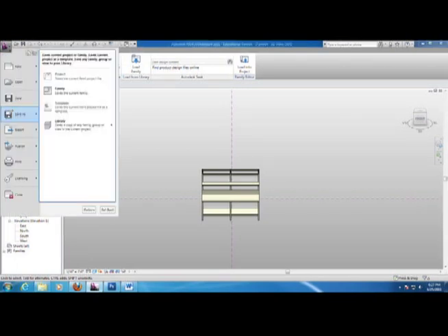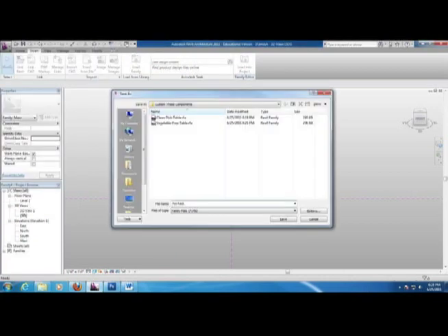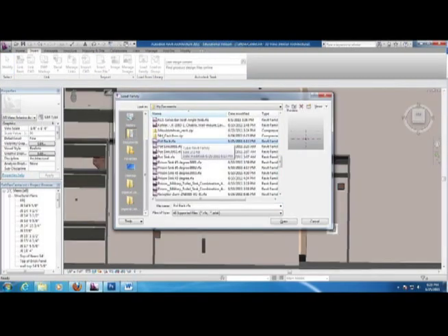Next, click the Revit button in the upper left-hand corner of the screen. Select the Save As option, then click Family. Name the model, and make sure that .rfa is the selected file type. Close the Conceptual Mass Creator and open the project in which the component is to be placed. Click Insert and select Load Family. Select the .rfa file that you created and click Open. The model is then loaded into Revit.